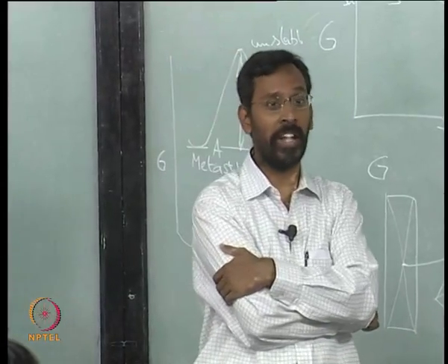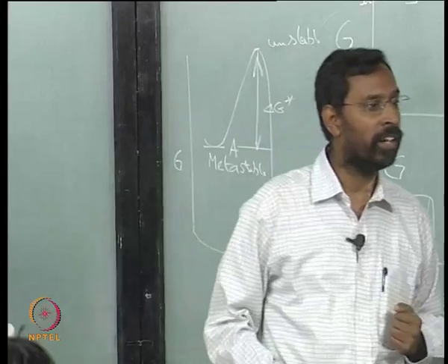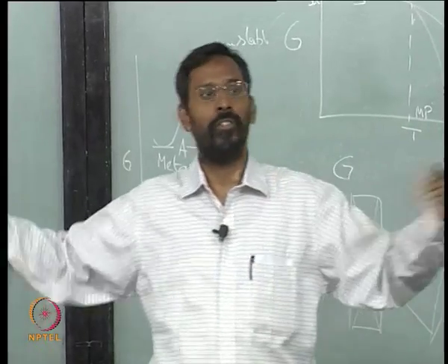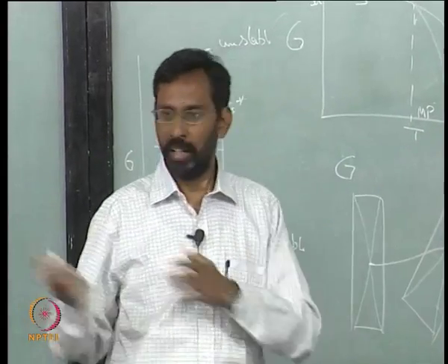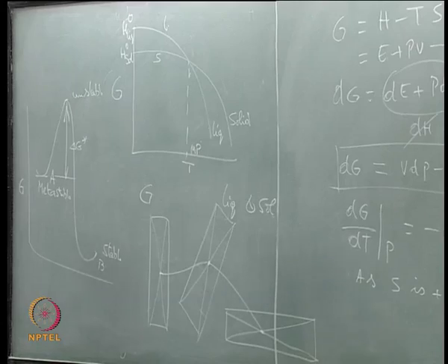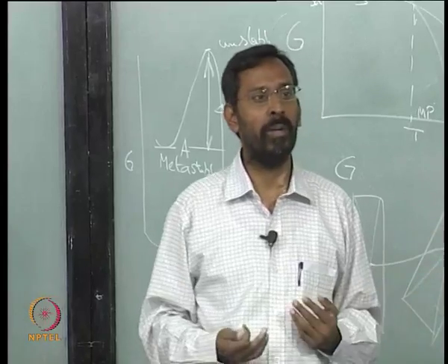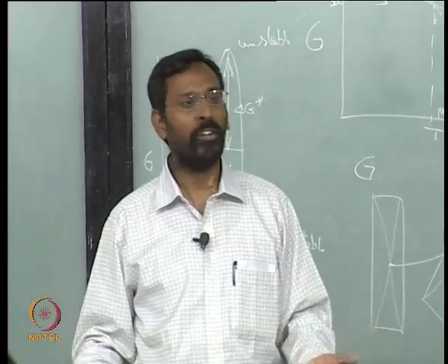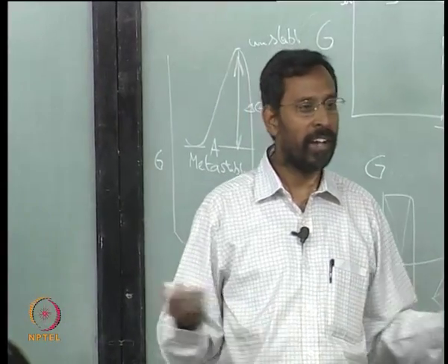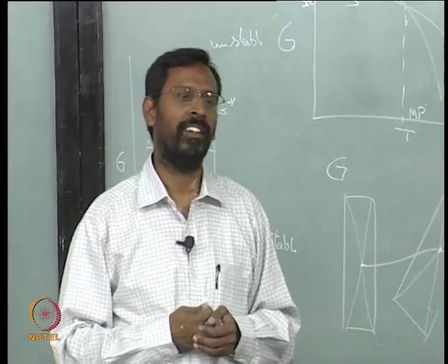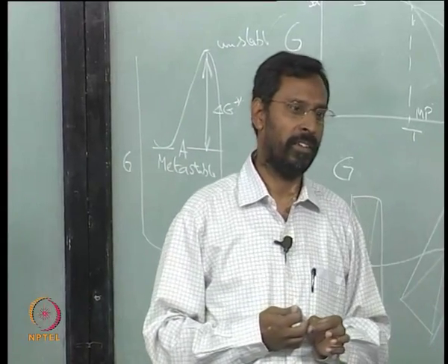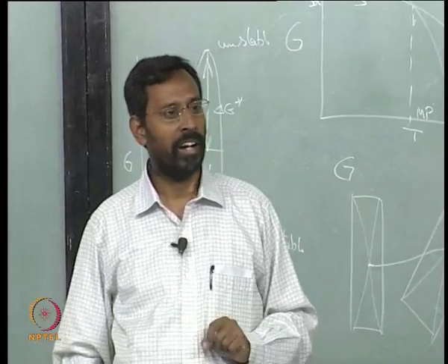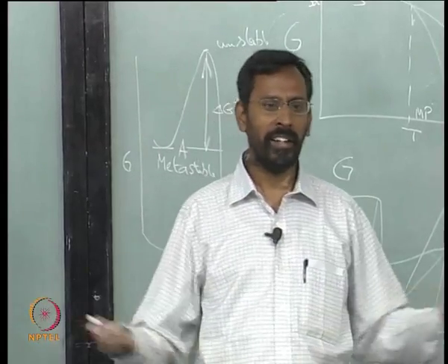In principle, if I take this cementite to a higher temperature and heat it, it becomes ferrite, or alpha iron, plus carbon, graphite. In principle, cementite is not stable, but we see in steel at room temperature, cementite exists forever, for ages, and nothing happens to it. You make a mild steel and just leave it, and the cementite remains as cementite.